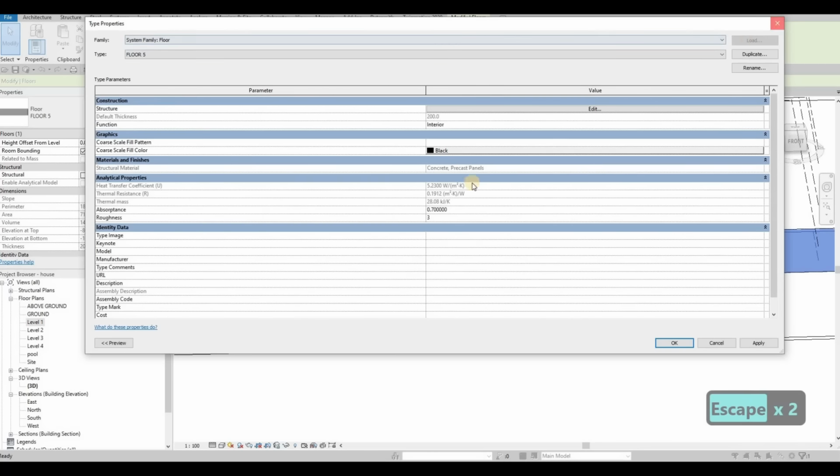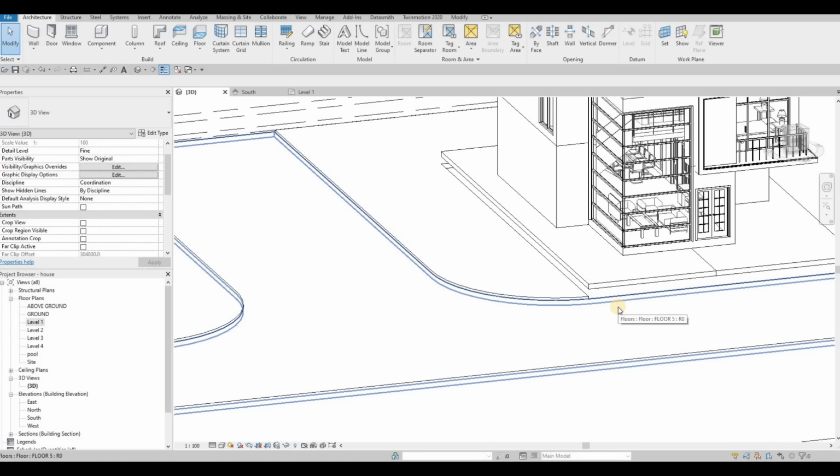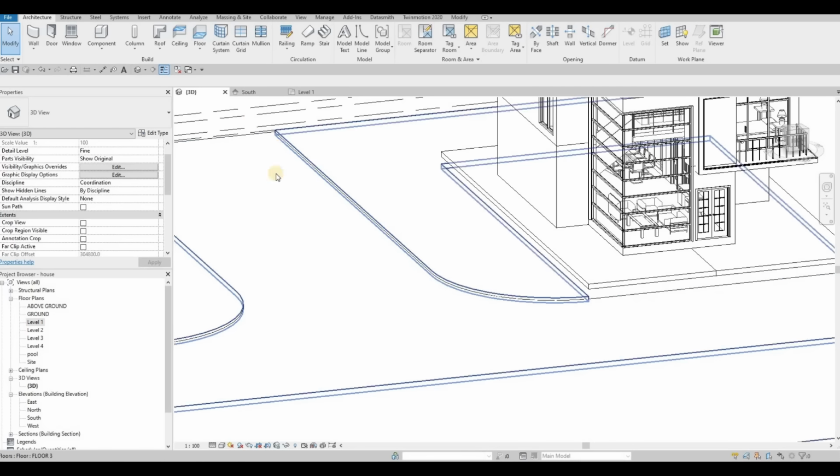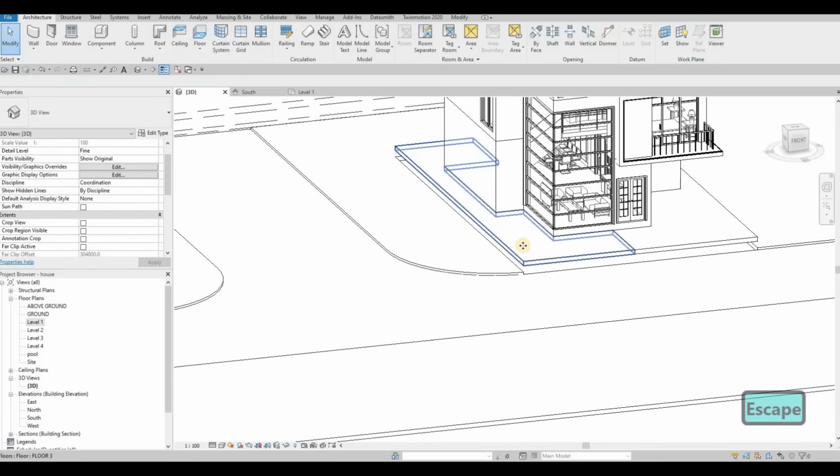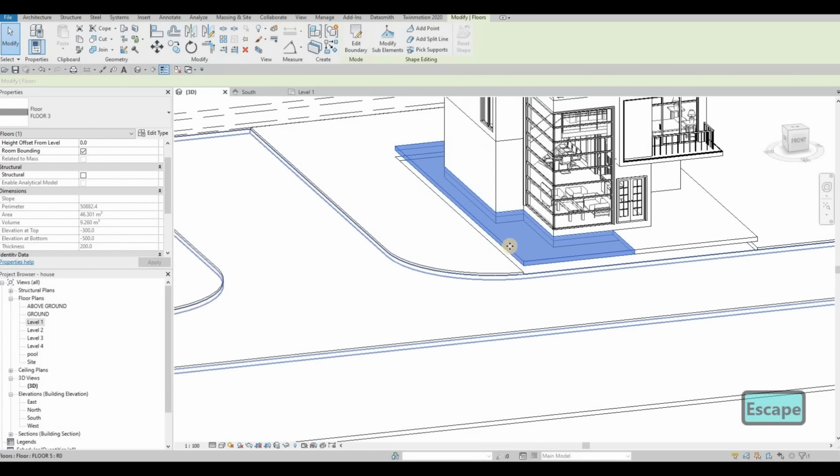So here, base offset -100, and then we're going to add in the sidewalk as 100 for the thickness as well. So it will look nice here. It will look flush with the grass, and then a grass, and then another grass that is inclined.